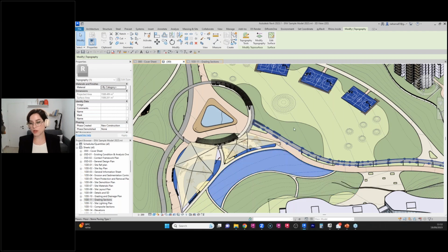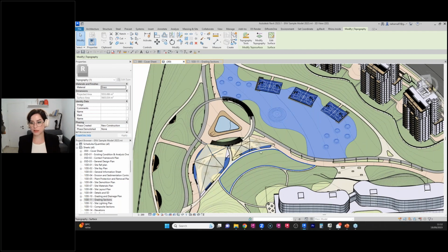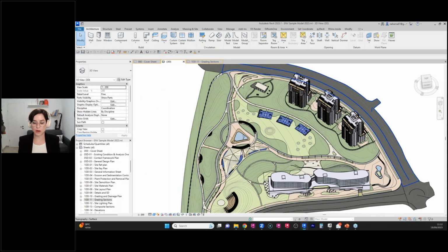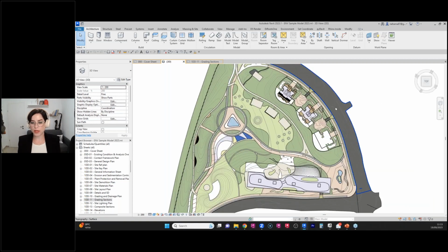So using environment tools, you'll see that you will have to do very little calculation for these secondary surfaces. And the most work would be for the primary ones. These are the ones that really build your design, connect between one elevation to another, one area to another. The third principle is that if you're transitioning from CAD to Revit and you're used to doing everything on a